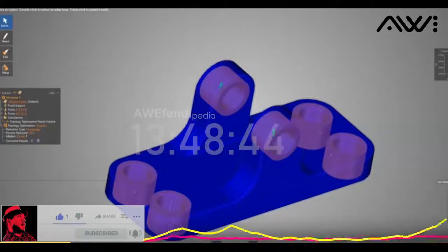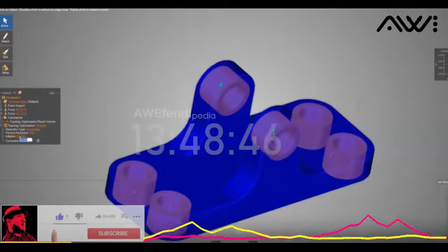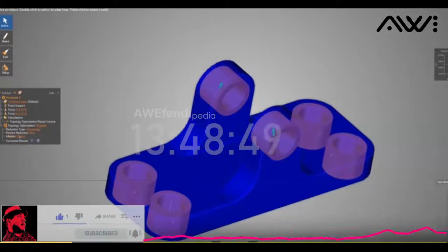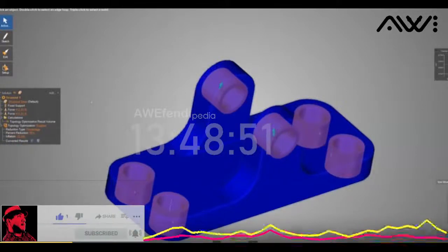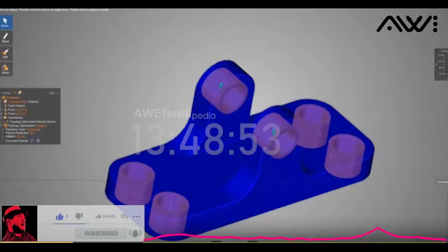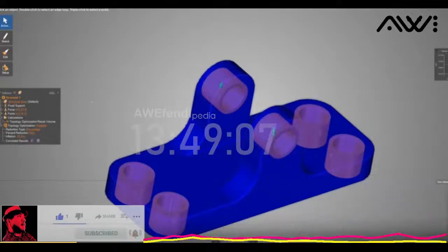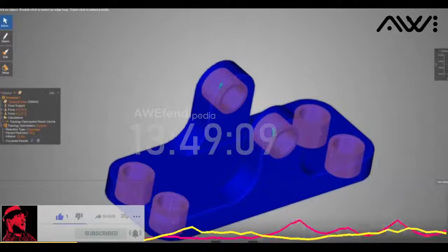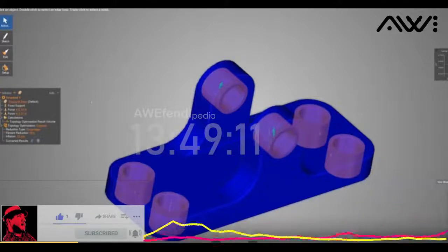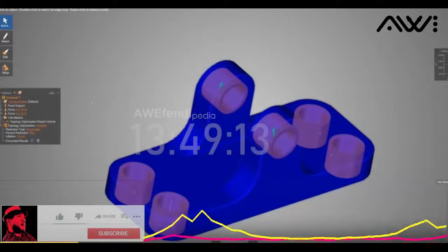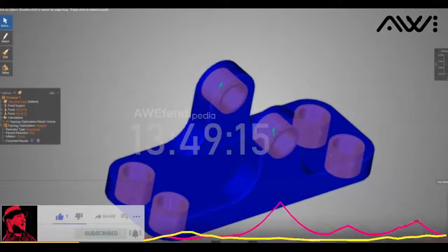And then inflation. Well, what inflation means, if I go ahead and change this, let's make this fit. What you'll see is this is my keep out zone, based off where stresses are at the top, at the 4 bolts, and where the forces are happening. These are my keep out areas. So don't get rid of them for me. Optimize everything else. And what we have the ability to do is keep it actually simple.